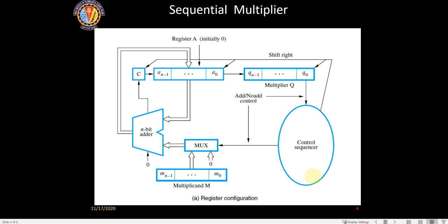Once we learn about microprocessors, we'll see that depending on the instructions, each instruction has a known number of clock cycles: for an add operation these many clock cycles are required, for a divide operation these many, and just to move one data from place A to place B these many. They are all known to the microprocessor. So once we give the microprocessor a command, it will automatically know how many clock cycles are required and act accordingly. Is it okay?